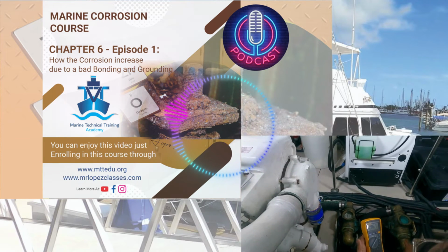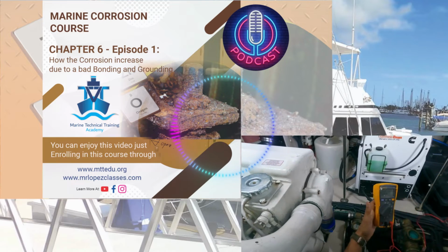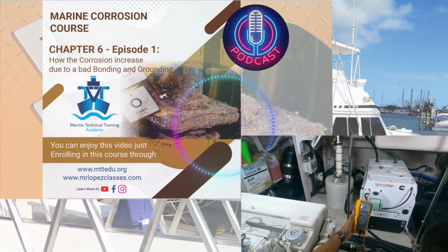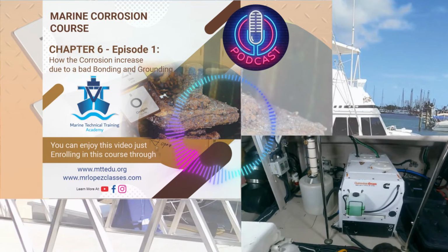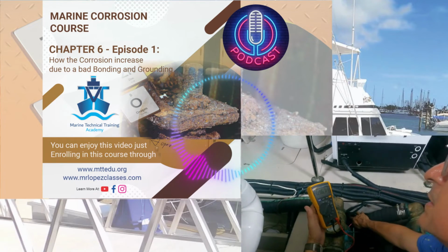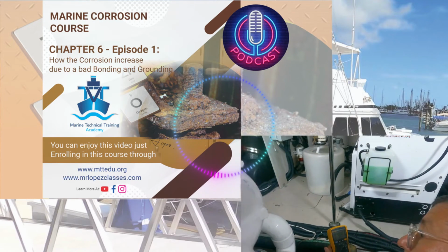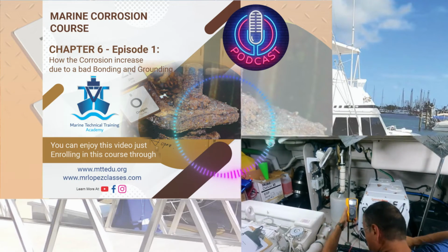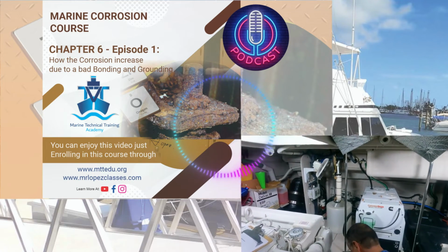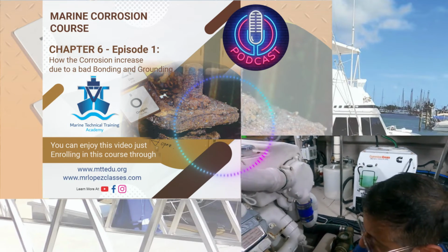There are two possibilities. When I connect the shore power of my boat into the pedestal, if the pedestal of the marina is not good, if the ground of the marina, if the ground of the building is contaminated, that contamination, that bad ground enters my boat and affects my boat. This is one possibility.